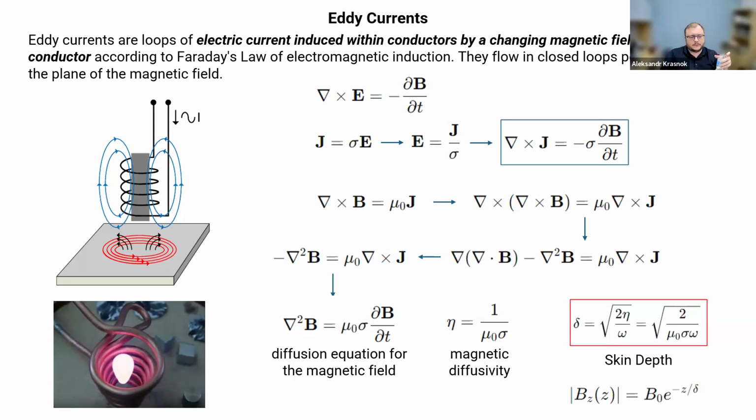Okay, so metallic objects at high frequency don't dissipate energy in scatterings, reflections. For example, the vast majority of microwave antennas are metallic, exactly for this reason, because they are more efficient because of this very small skin effect.